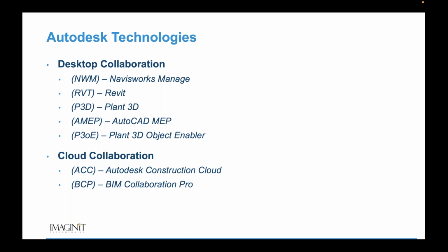The Desktop Connector gives me the ability to basically tie the Windows operating system on my computer to the cloud-based Autodesk Docs project environment so that I can access information through the Windows File Explorer, and that will help to facilitate the sharing of data between my plant and my Revit projects that may exist up in the cloud for collaboration purposes.